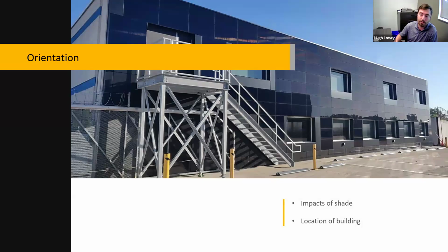So you're not getting any direct sunlight. You're actually getting sunlight that's bouncing off molecules in the air and then somehow hitting that wall on the north side. And like I said, that's about 30% of the power that you would get from the south wall. So the takeaway here is it's not worth doing the north wall. It could be worth doing the east and west wall, depending on orientation of the building, but you really should be looking at your south wall in order to maximize solar capture in the northern hemisphere.